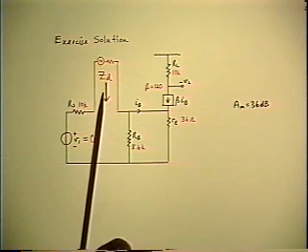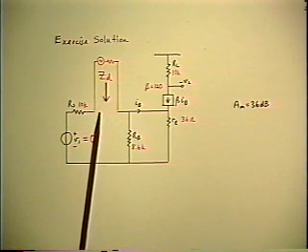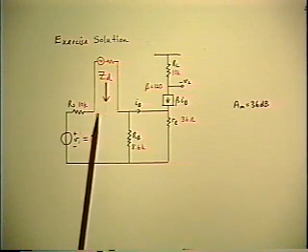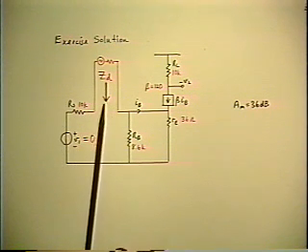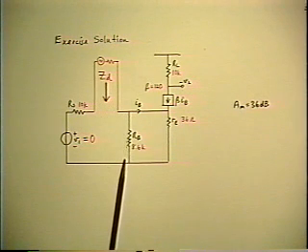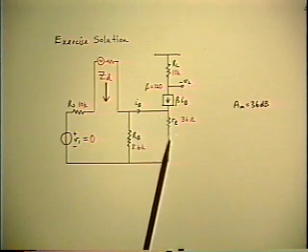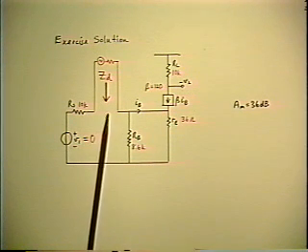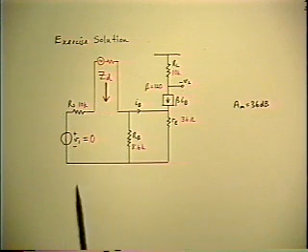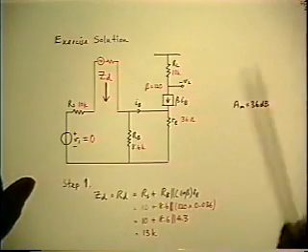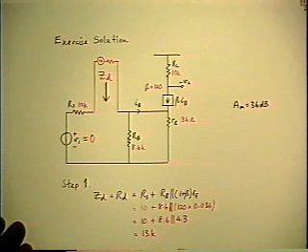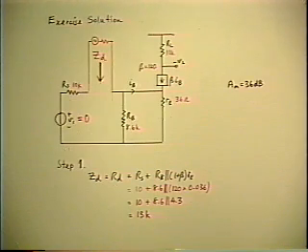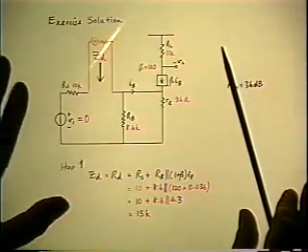Well, let's follow through the argument. Single injection. So you want to know what is the impedance looking in between these two terminals. If you look to the left, you're going to see RS to ground. If you look to the right, you're going to see RB to ground in parallel with the reflected RE. So the total impedance is the sum of what you see looking in the two directions. So the result is RS plus RB parallel the reflected RE. Okay, that's the single injection calculation.